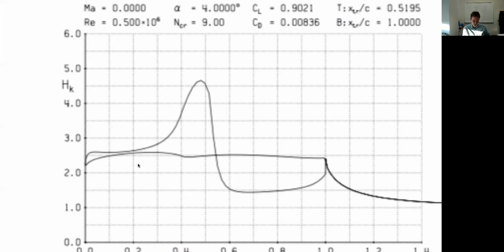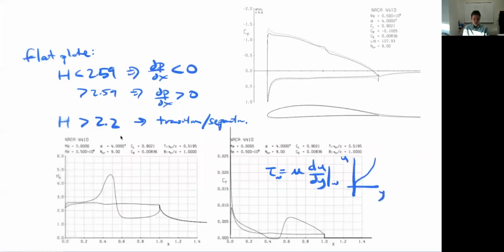And again, we notice here this large C_f at the beginning, as we saw in the Blasius solution, because it was divided by the square root of Reynolds number as a function of x. So there's a square root of x on the bottom, so it becomes really large with small x. So there's a very high skin friction coefficient towards the nose, it comes down, we separate, and it goes back up again here in turbulent flow. Okay, so that's it for today.